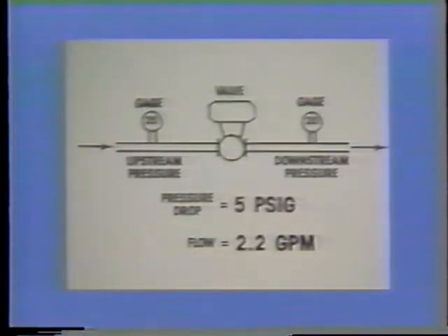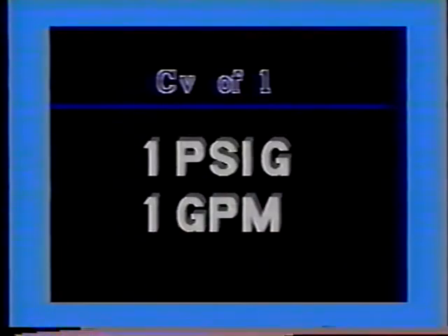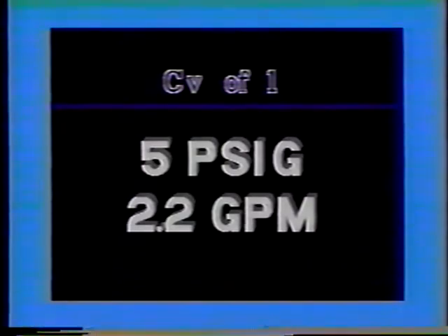As the pressure increases on the upstream side versus the downstream side, the pressure drop increases, and the rate of flow increases through the valve. The capacity index provides a reference point at a 1 psig pressure drop, which can then be translated into the volume of flow at any given pressure drop that is greater than 1 psig.